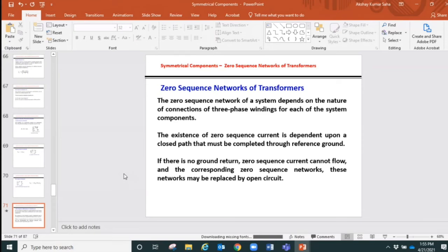Is that clear? If we neglect the no load current I0. Okay, thank you, sir. So if we neglect the no load current I0, and if we find that there is no load, meaning the secondary is left open, there will be no reflected component of the secondary current on the primary side. And that will be useful now for us.